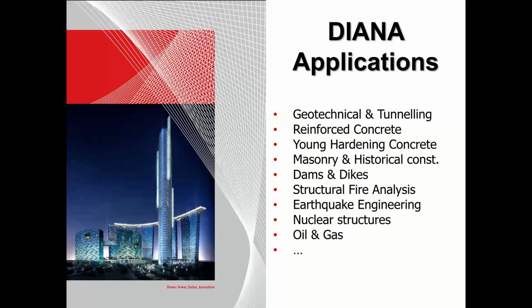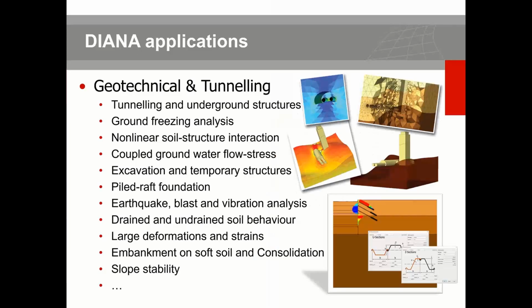With respect to Diana applications, I will quickly go through some of the main key features and activities. We start with geotechnical and tunneling. We have a very good integrated solution for all types of geotechnical and tunneling applications. You can use the integrated environment of Diana for any types of tunneling and underground structures, for ground freezing, also called the three phases analysis, and for real soil structure interaction. If you have some sort of interaction between the underground structure and the surrounding soil or rock, you can model it with the concept of nonlinear interface behavior, coupled groundwater flow stress analysis, slope stability, and many more.